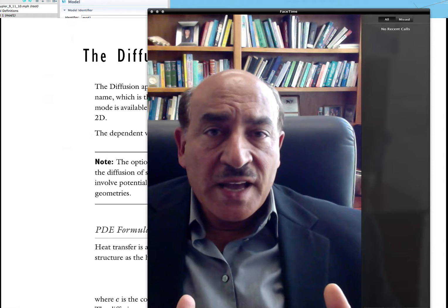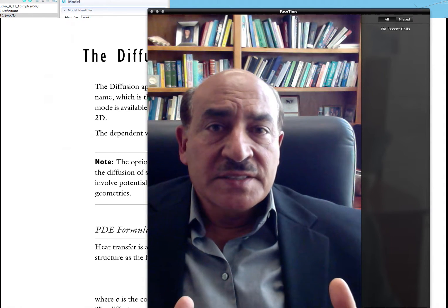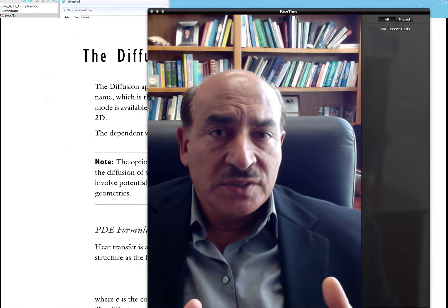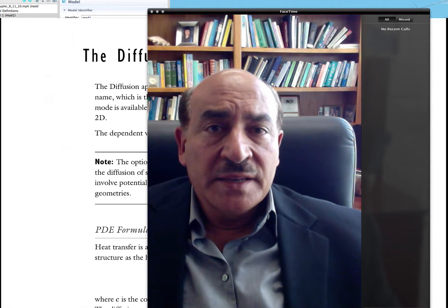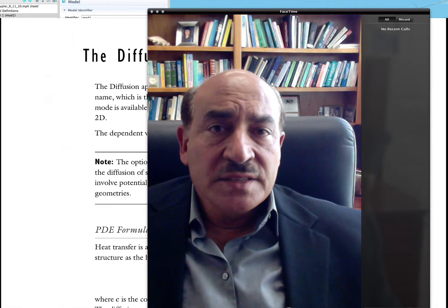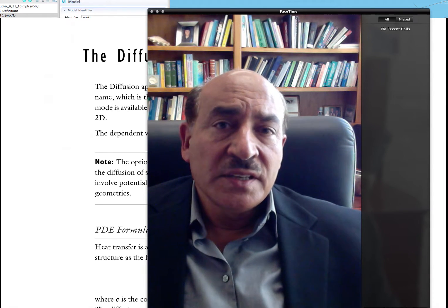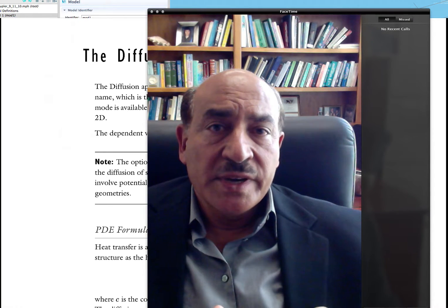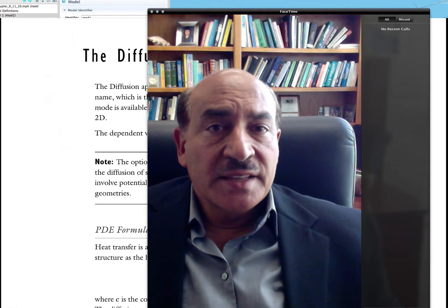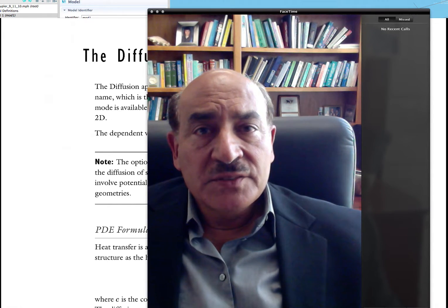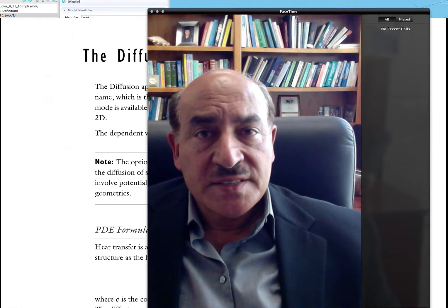If we don't do that, then we have a static body that can be a solid or a liquid, and for this static body we would solve the same energy equation, which was reduced to a conservation equation for the thermal energy. That equation becomes the diffusion equation. And the diffusion can describe diffusion of temperature, or it can describe equivalently the diffusion of mass or species.